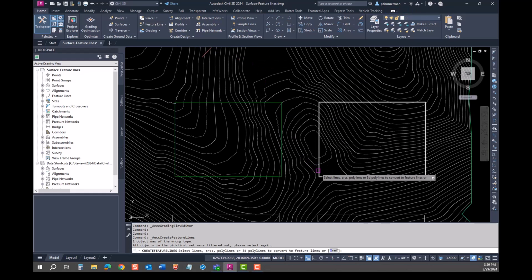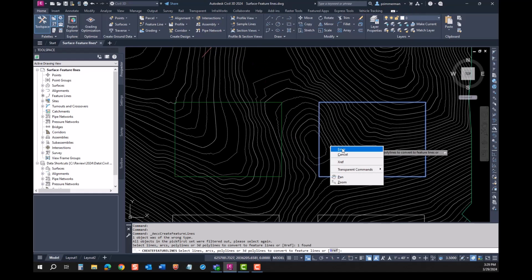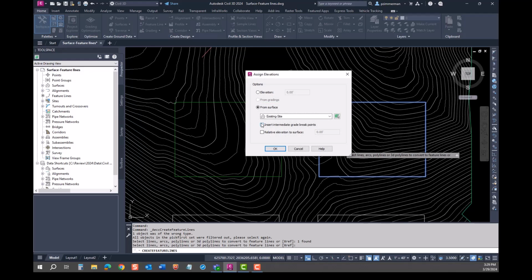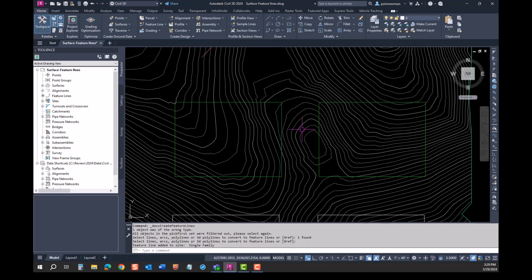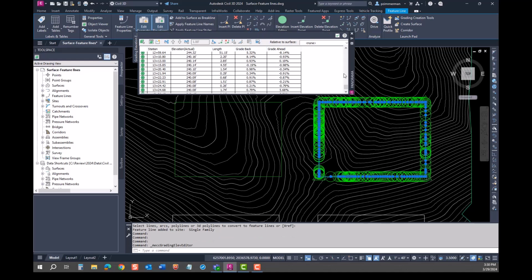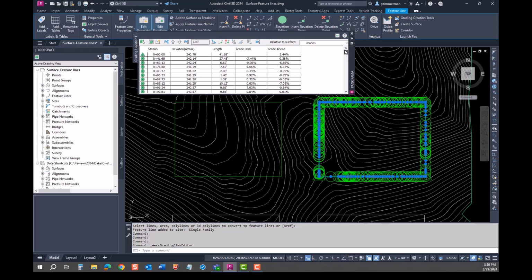Learning how a feature line acts when in a site or not in a site. How to draw or convert AutoCAD entities into feature lines. How to extract feature lines from corridors. Applying the geometry and elevation editing tools to existing feature lines. Using temporary surfaces to incorporate slopes or grades into a design. How to use various grading editing tools to avoid incorrect solutions.